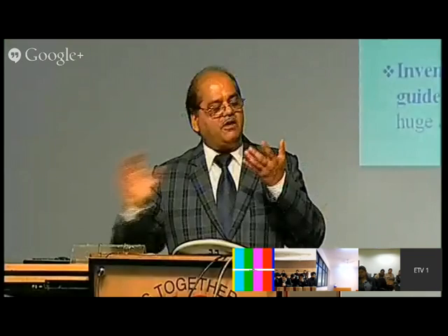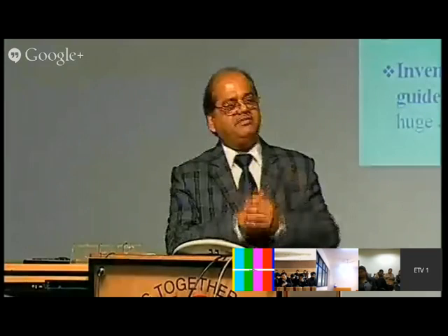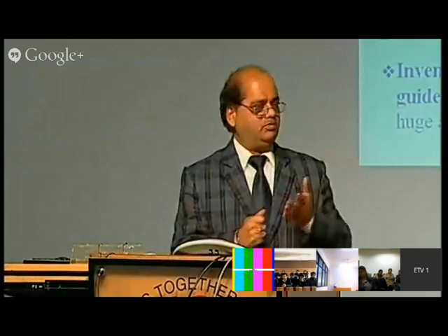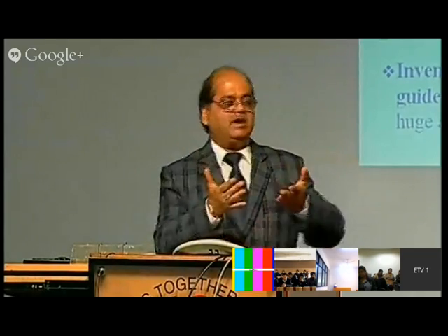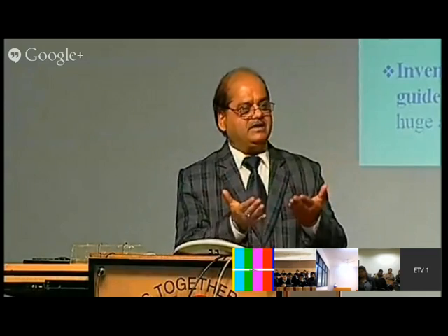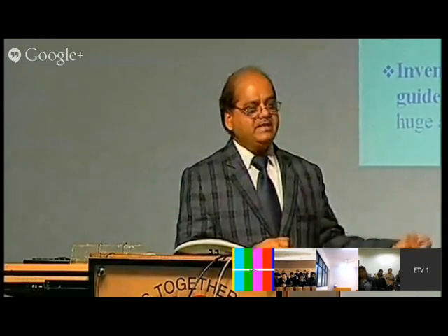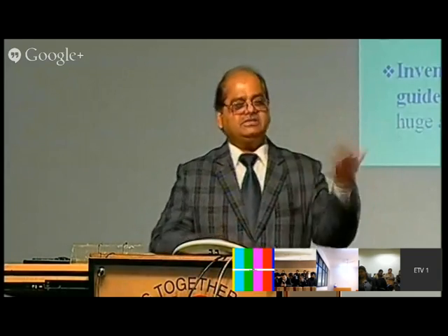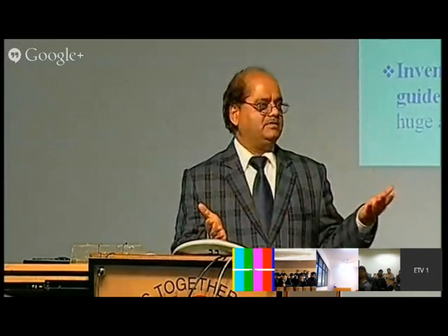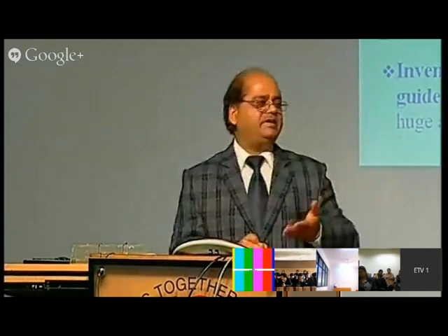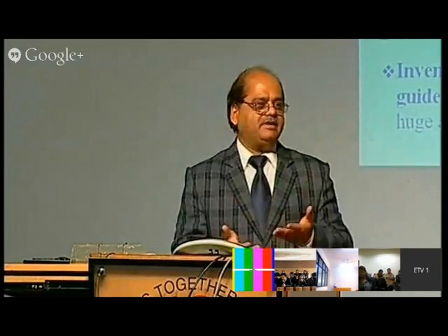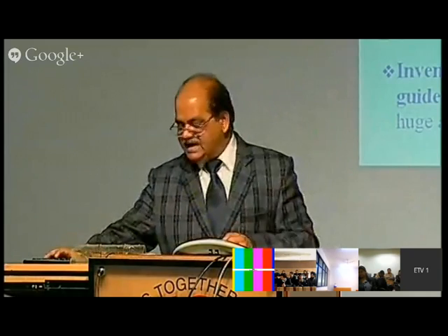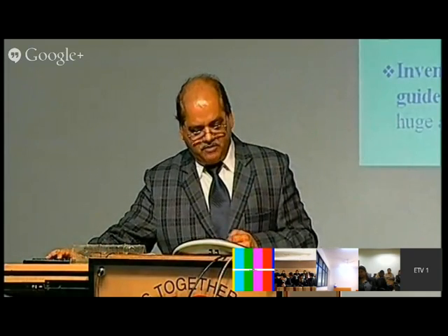But the optical fibers which were available at the time of invention of the laser were very lossy. The losses were not very low. Because if you are going for an alternate communication media, the losses should be comparable to the existing media. We were using copper or coaxial cables as the communication media. The losses were around 20 dB per kilometer. So if you are going for replacement of these types of conductors with the optical fiber, you have to reduce the losses to a low level, at least a comparable level. That was the idea that led to development of communication.